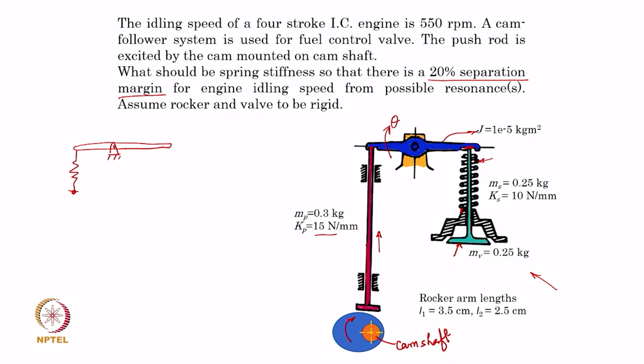So, this itself can be modeled like a spring, but it is not a normal spring. We just saw how the spring's own mass can influence the natural frequency. So, by giving the mass of the push rod, we can, if we want to, consider the mass of the spring in the analysis.